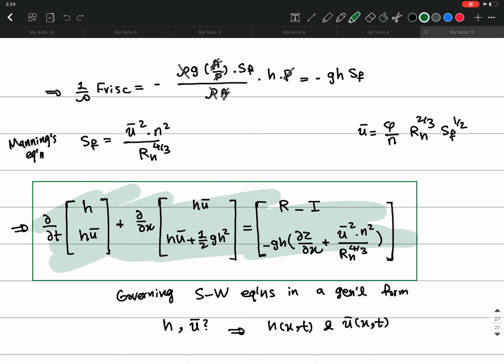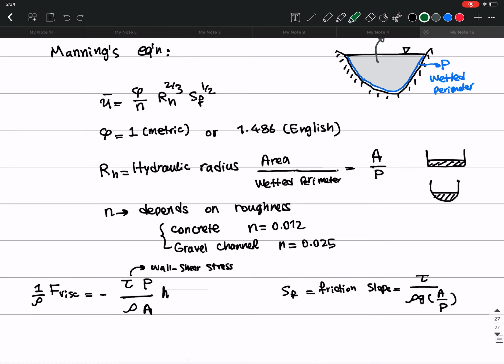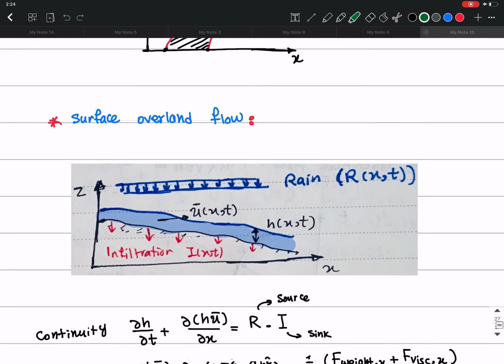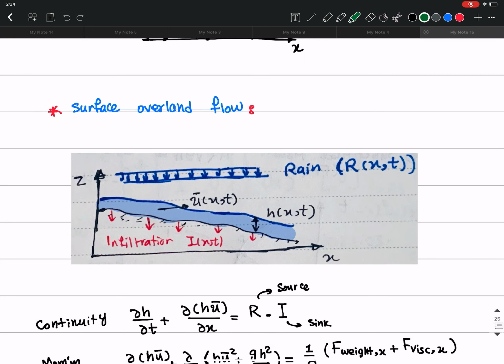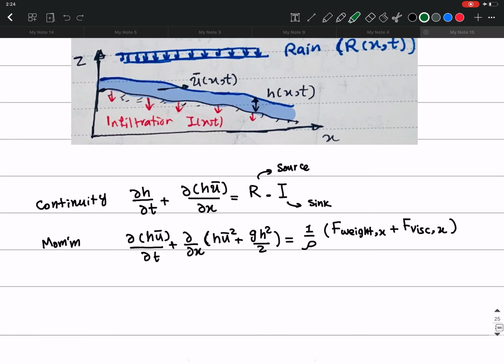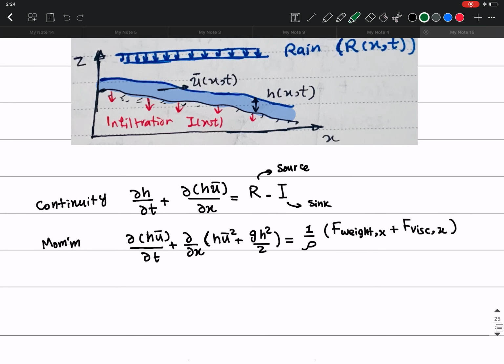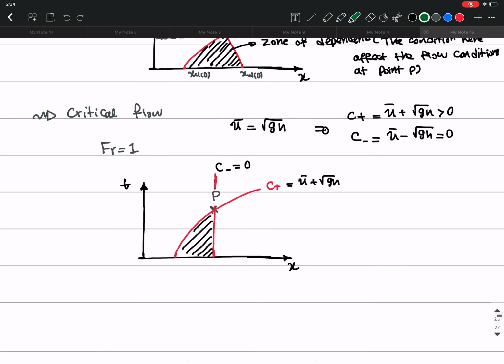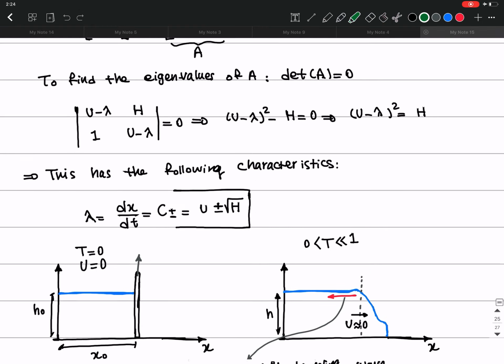For example, I think HEC-RAS and a lot of other tools, like in flood routing, for hydro routing, all use these shallow water equations because they are a much simpler form of the momentum and continuity equations, obtained by using the shallow water assumptions. Okay, so this makes the flow much simpler.